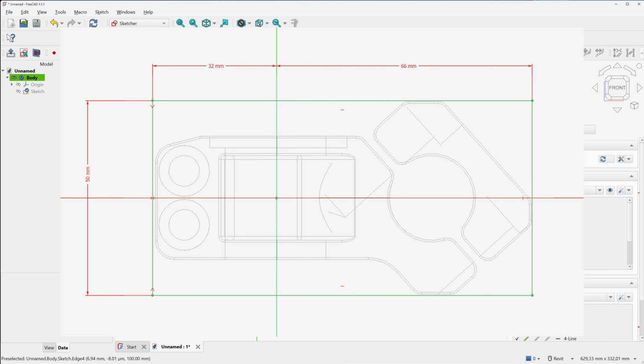The answer is simple. I want the green axis to correspond to the location of the stem hole that joins with the fork. Later, I want to be able to easily modify the length of the stem, the value of 66, which will make it much easier to create a variable. Plus, the red axis corresponds to the center of the stem. When I place the handlebar hole, I'll be sure to always be right in the middle.